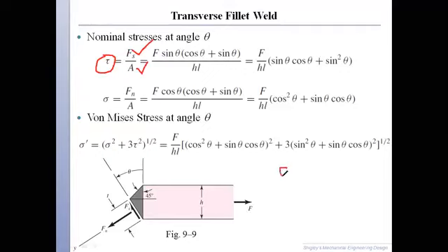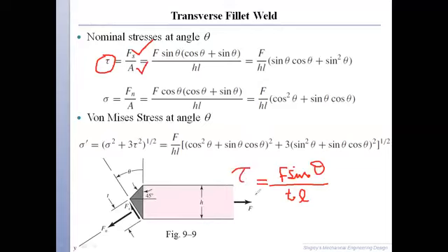That is F sine of theta, divided by T times L. This is what we said our stress would be. Now what is the value of T? T is H over cos theta plus sin theta.